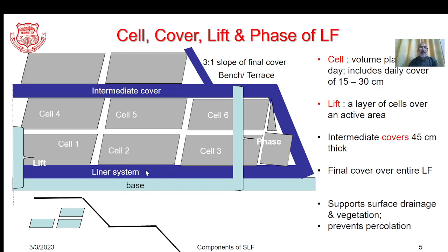Again, the features of that we'll be discussing in depth as we move ahead. As we see here, this is a certain intermediate layer of 45 centimeter thickness, and these sides are maintained with a certain slope, say 3:1, and it is creating certain benches as well as terraces in order to maintain that particular facility subsequently.